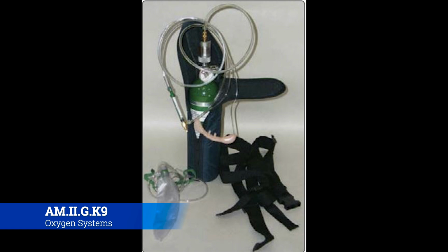So imagine you have a corrosion point on the inside wall of the cylinder that you can't detect, but then you put it on an airplane. It flies up to high altitude. It's under a high level of pressure. You can have an explosion in that tank. So it's really crucial that these tanks are maintained properly, because you can't really see the inside unless you do a lot of test work afterwards. So it's just better to make sure that they are maintained at or above 50 psi.